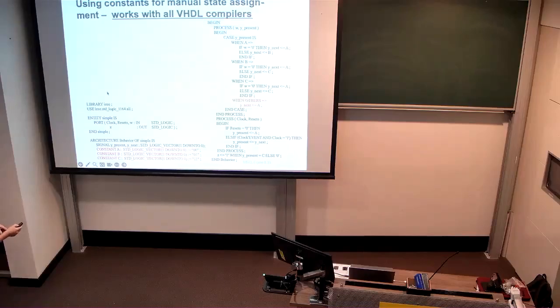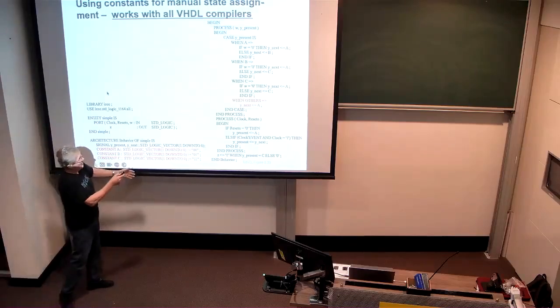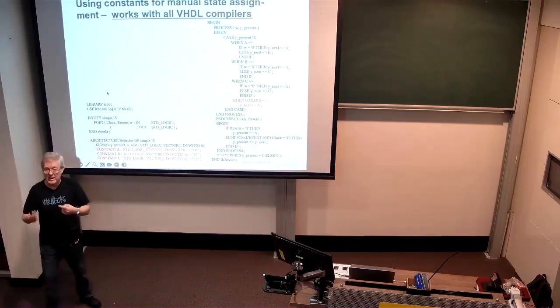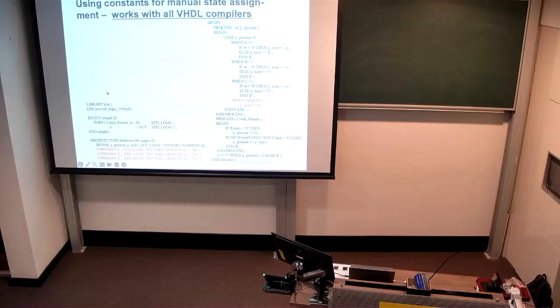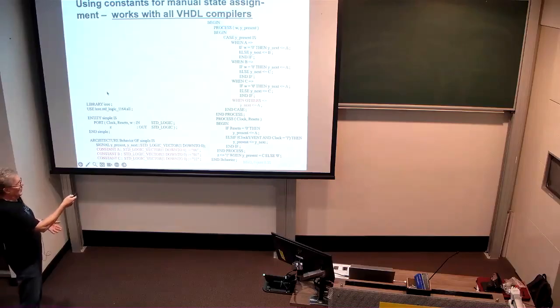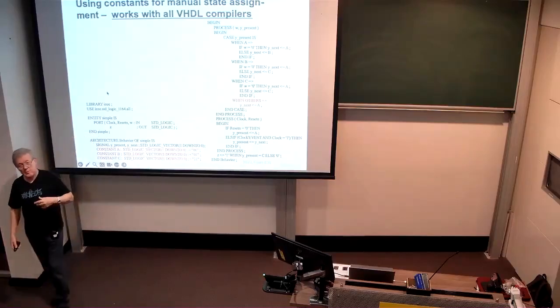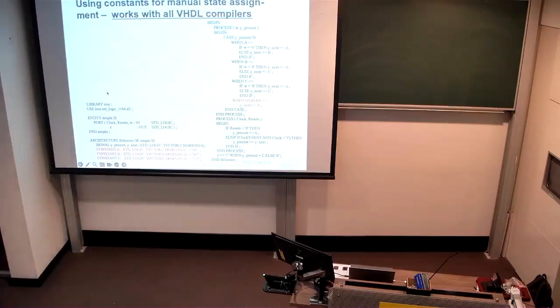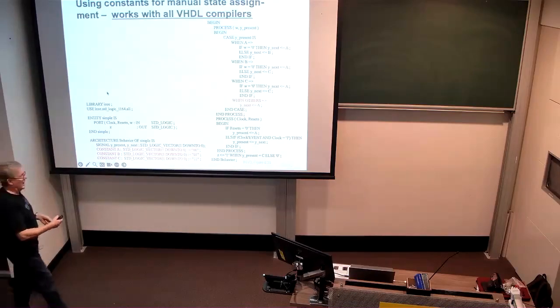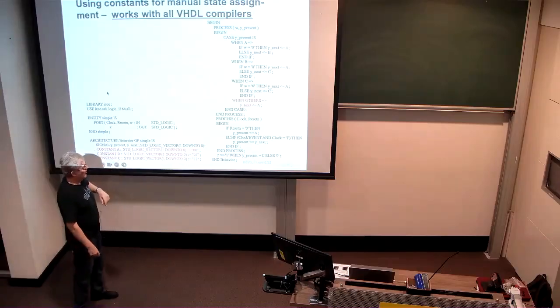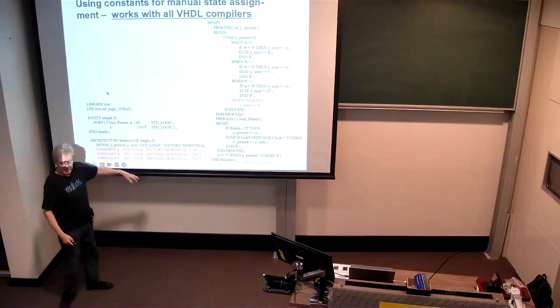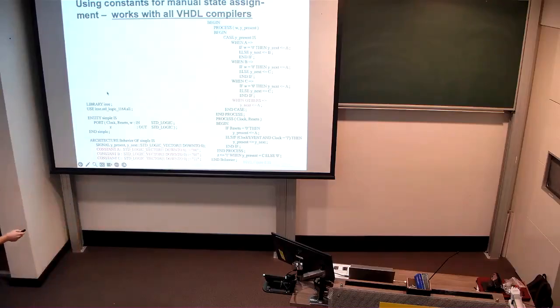The impact of that, because we're now using standard logic vectors, when we come to our case statement here, we can't rely on the fact that we've only ever got states A, B, and C. We've also got the possibility that this standard logic vector that we're checking, y present, which has got to be a 2-bit vector, might have, well, 78 other values, right? So we have to have a when others down the bottom here to catch all of those non-standard, non-defined states, okay? So that's a consequence.